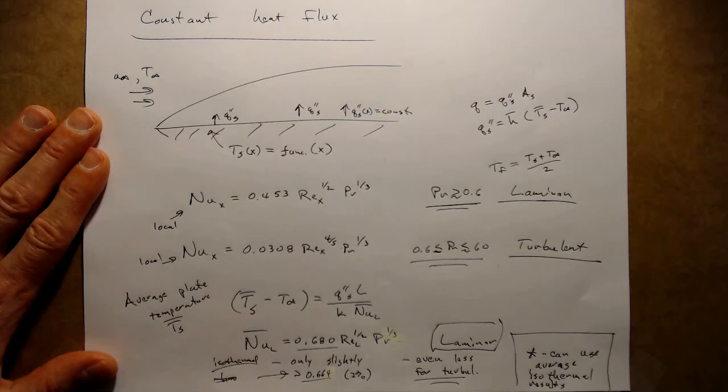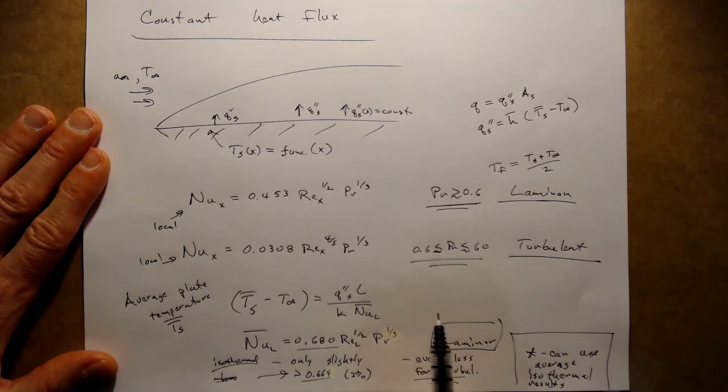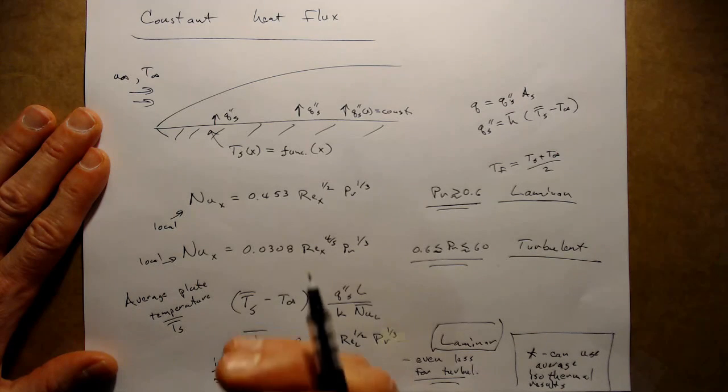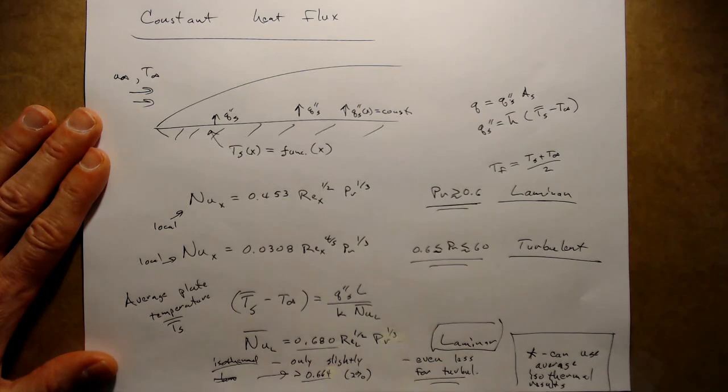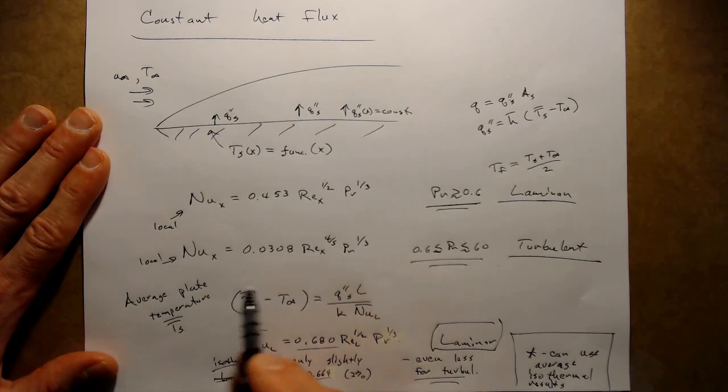And we also want to be really cognizant that these correlations shouldn't be considered to be particularly exact. They're based, many times, on the accumulation of a large amount of experimental data, and this describes a good relation of the average of that experimental data, or the most common result from that experimental data. But experiments always have noise in them, and the conditions are always different between different cases. And so these correlations can have rather large variations between the Nusselt number that the correlation gives you and what you may find in experiment.